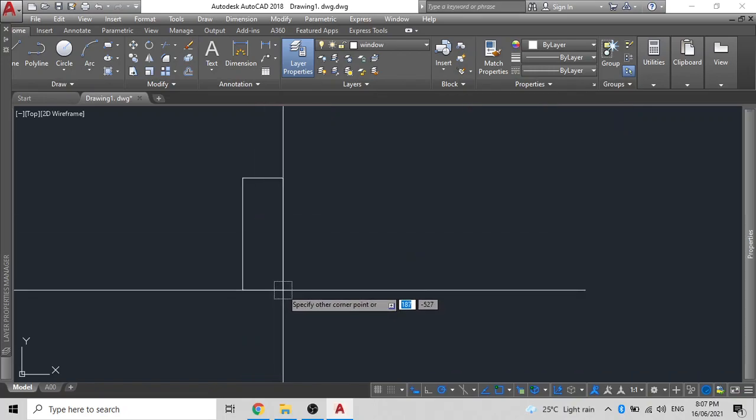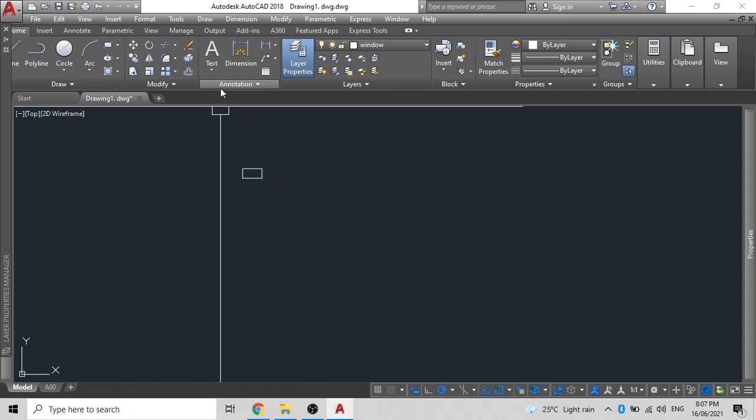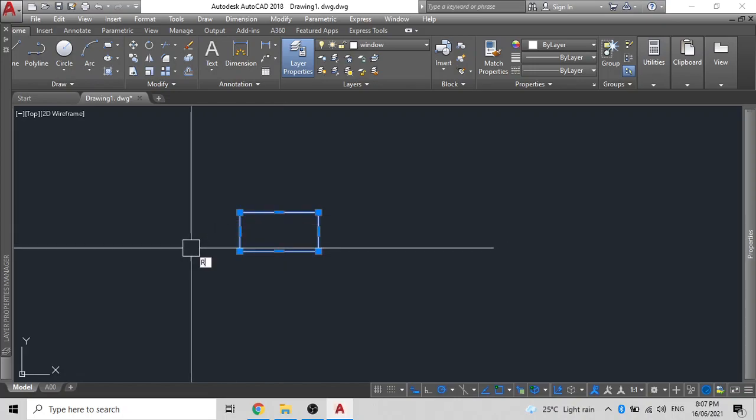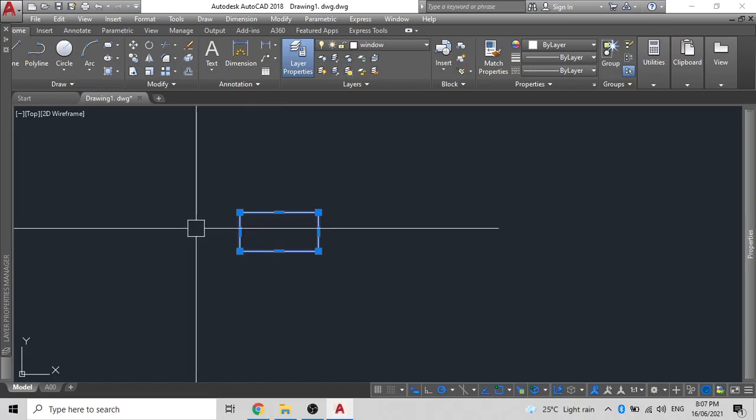Now a door jamb, remember there is a big difference between rough timber and dressed timber. In Fiji, 100 by 50 translates to 90 mm by 45 mm dressed. So do not put 100 by 50 here. Use the dressed dimension of 90 by 45 and press enter. You can rotate this.